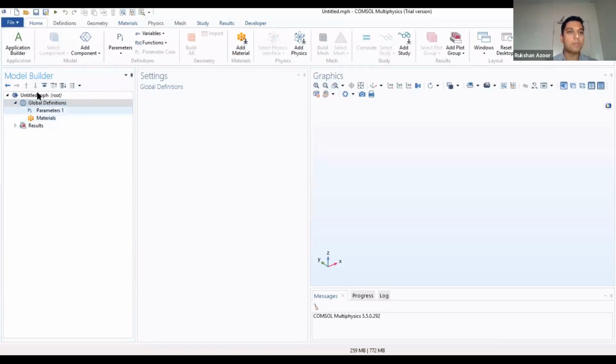Yes. So that is because your physics has not been set up yet. So go to the physics tab on top of the ribbon, right on top. Which one? Physics, right? Does it work? No, I can't click on that. It is shaded, like gray color.